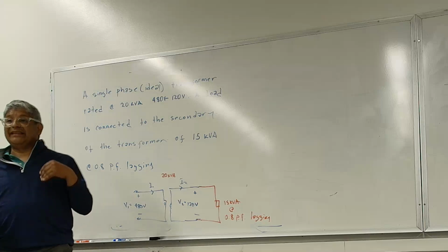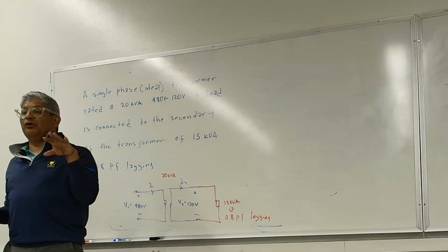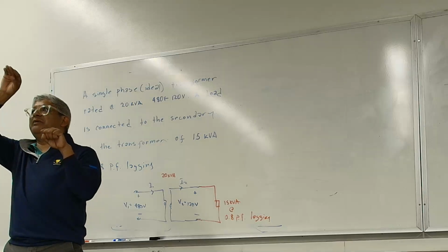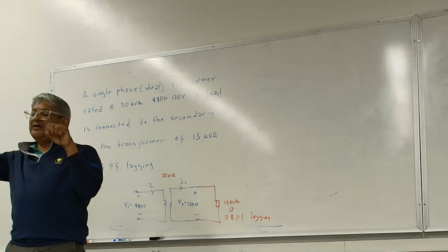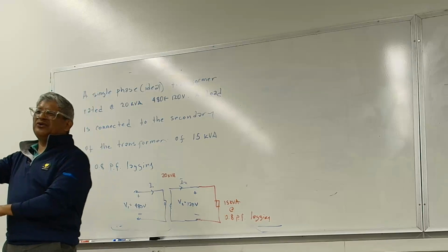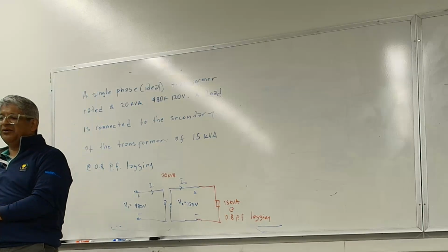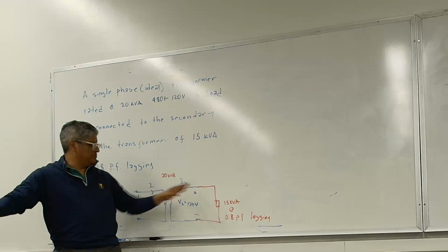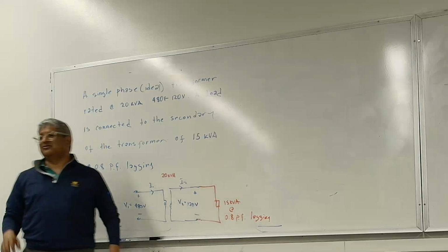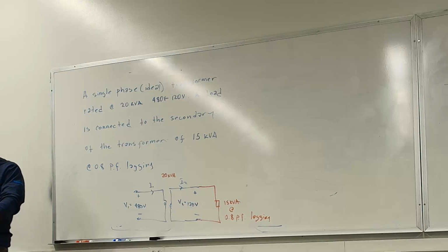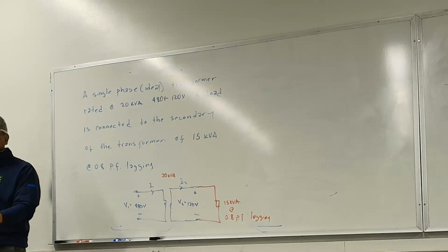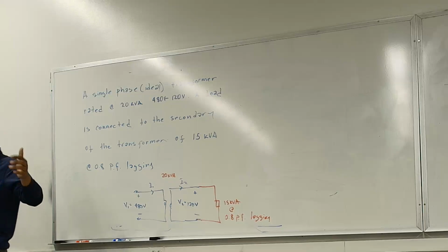So transformers, once again, have a load profile, we call it that. You're going to run maybe, I don't know, 110%, 120% for like 6 hours. But then I know that during the night, the load is going to come down to maybe half of it in some cases, right? So you're giving the transformer a cooling period. That's how the system is designed, that you have that cooling period, and then you can extend the life of the transformer.